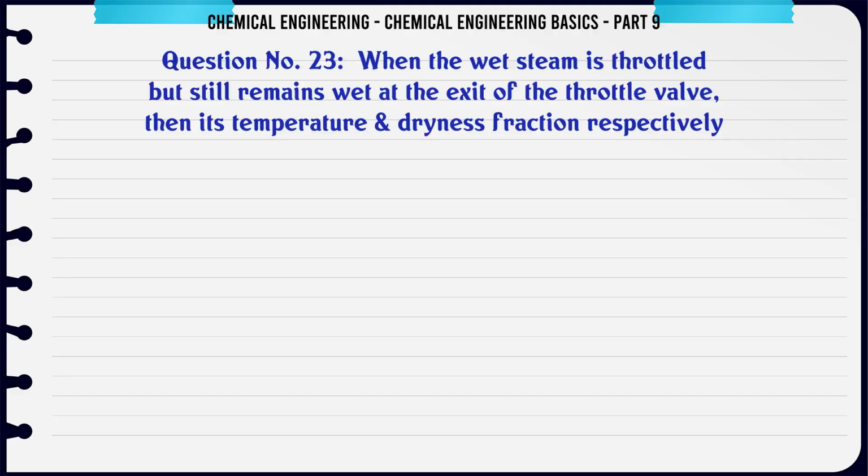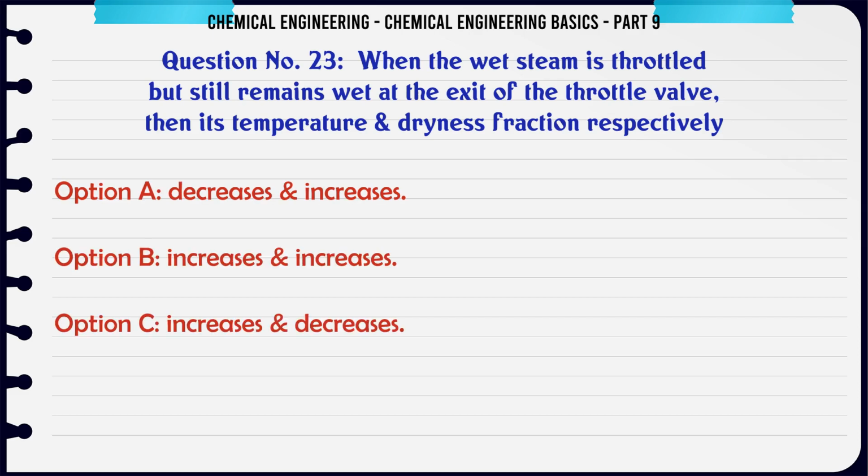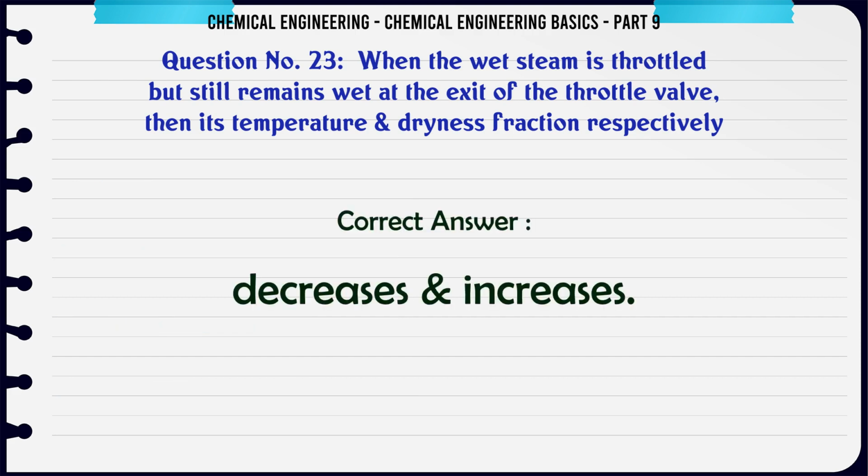When the wet steam is throttled but still remains wet at the exit of the throttle valve, then its temperature and dryness fraction respectively: A. Decreases, increases, B. Increases, increases, C. Increases, decreases, D. Decreases, decreases. The correct answer is decreases, increases.